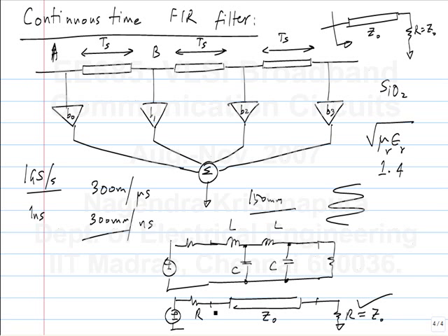So if you terminate it with the characteristic impedance of the transmission line, you will not see a periodic thing, meaning it is flat. You can also think of the flat response as a periodic response. If you have a different R, then it will have some response that is not flat but periodic. So in this case it is flat. What will it be in this case?